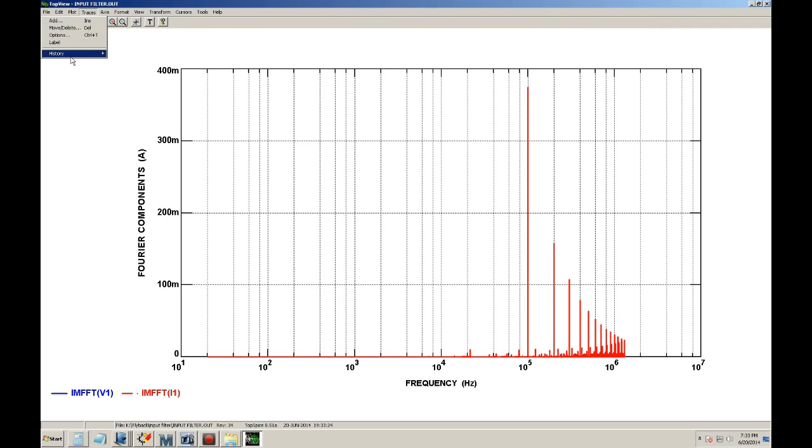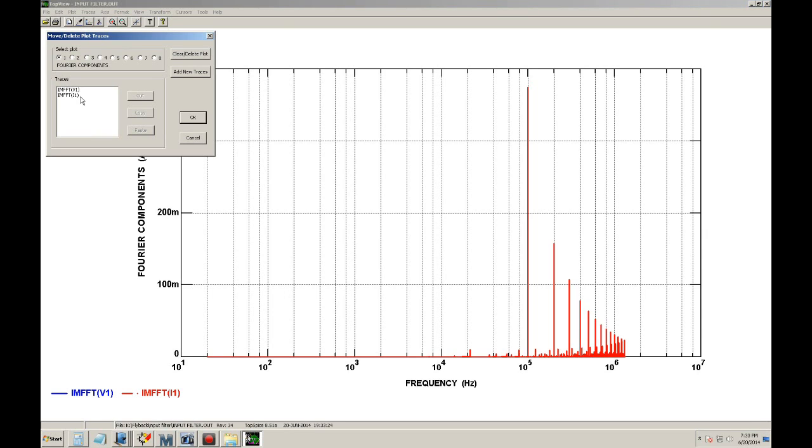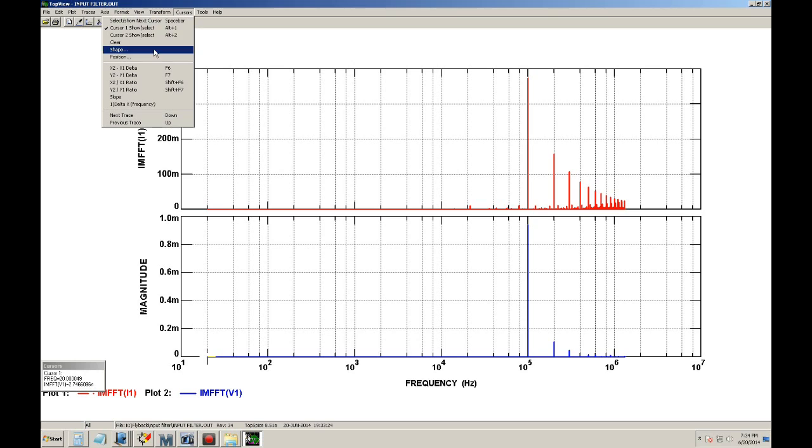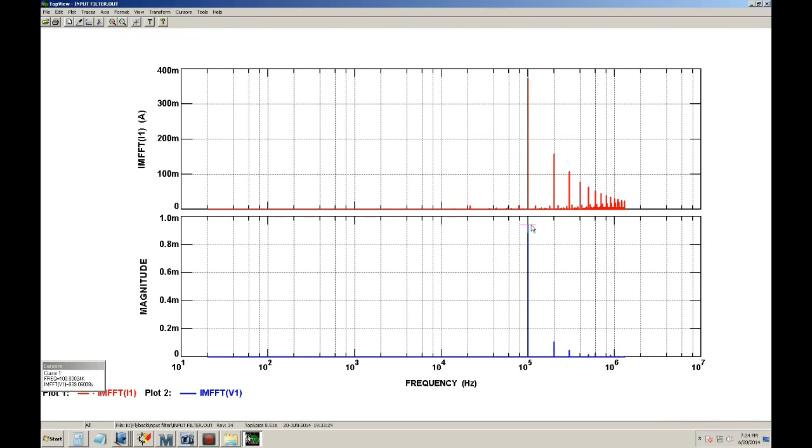Okay, here it is. Let me move this. I'll paste it in the second one. Okay, here we go. Let's go to maximum. Here's the maximum, and if you notice, it's 939 microamps. So that's the current going into the bus, and this is the original current that was being generated by the flyback. So we do see that the filter is working, we have just the right attenuation, and it seems to be working very well. You can also see that some of the other harmonics up here on the unfiltered are filtered even further.